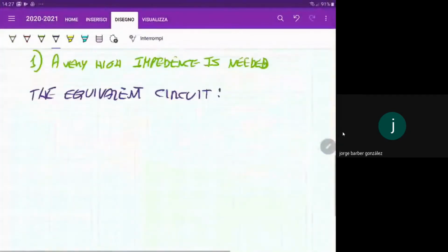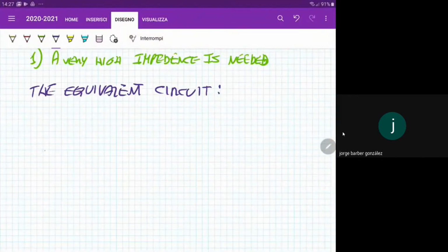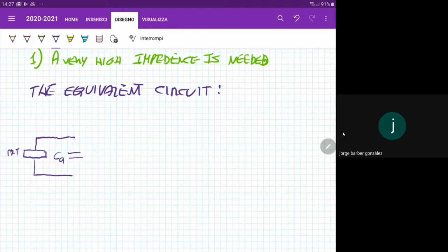So we can review that as the equivalent circuit that could be viewed as, let's say, the PZT crystal is there, and we can view that as a sort of generator. Okay, then this PZT crystal is characterized by a capacity, so viewing that as a capacitor, and also an internal resistance, RQ. I denoted the subscript Q because of the charges of the PZT.